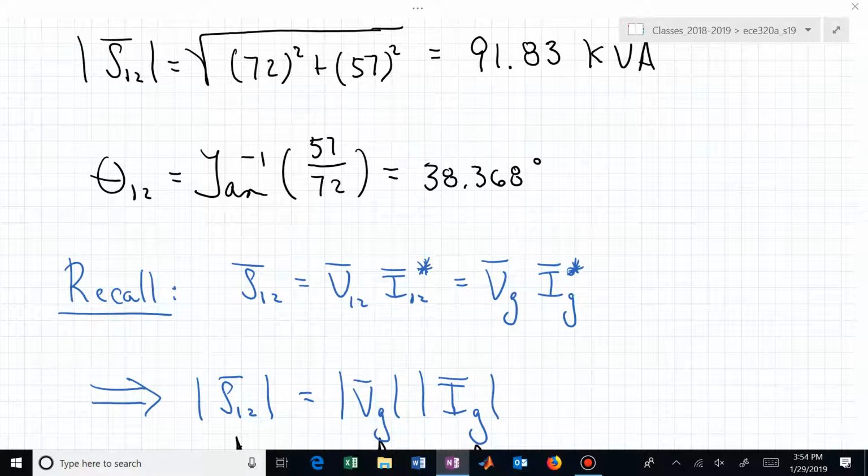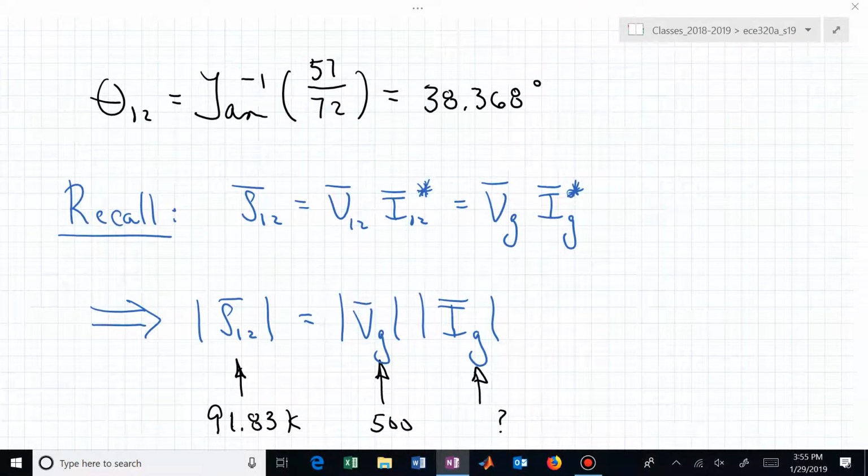But you don't even have to know that to answer your question. You can say, well, are the impedances the same? So are the complex powers having the same angle? That would mean they have the same impedance. And do the complex powers of load 1 and load 2 have the same angle? They did not, did they? So these currents don't have the same phase. So you could argue many different ways to conclude the same information.